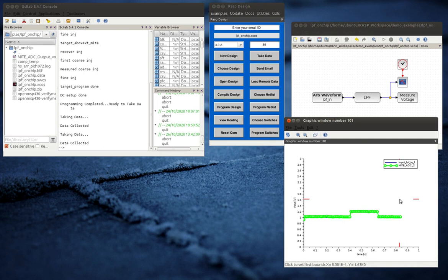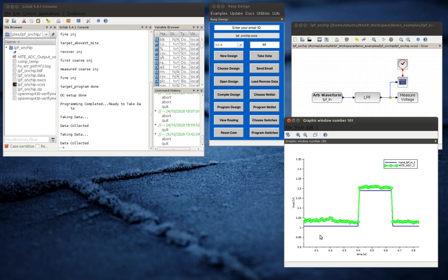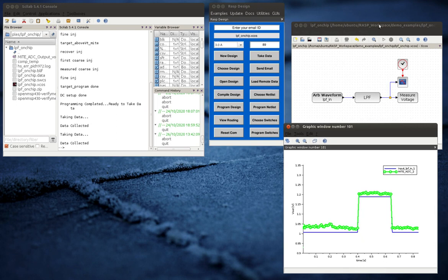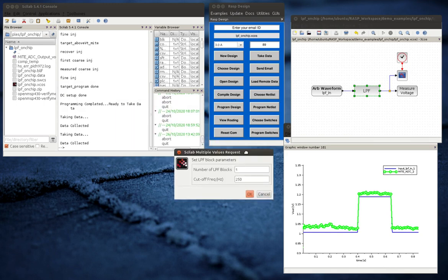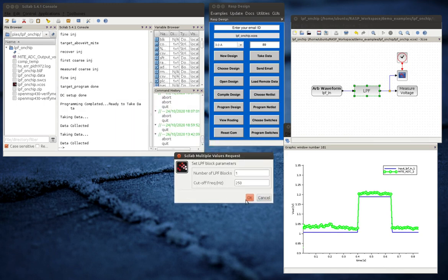The plot is available, but one of the things we're going to do is just go in and zoom in and look at the data a little closer. And you can see now what we would get is a pretty reasonably quick step up and down. Now we designed this for a corner frequency on the pretty low side. This is about 250 hertz, a rough estimate that we have on this particular function. This function is a little bit forward-looking in the sense of trying to use a cutoff frequency, to try to figure out a cutoff frequency versus just simply bias currents, but that's where we begin.